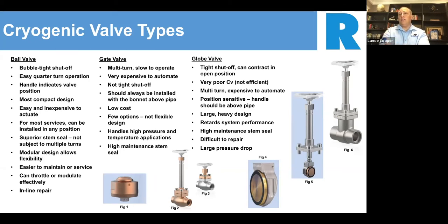But like I said, we see our short stem valves on our liquid dewars all the time, and they do what they need to do from that standpoint. It's a flat seated valve, very easy to work on, to be honest with you. Take them out and replace the seats and you're good to go. So that's an idea of those 3 types of valves.